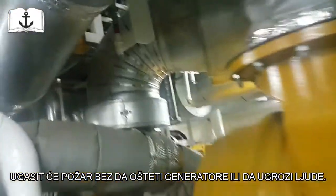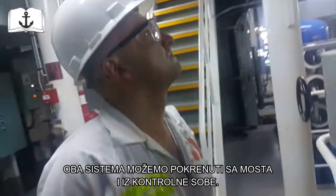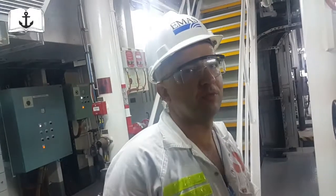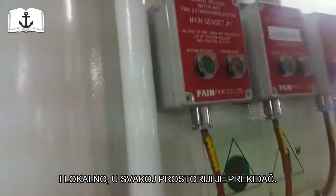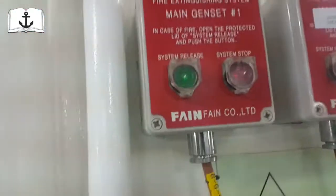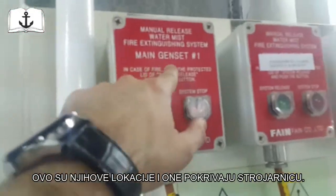Yeah, there's one more there. CO2 system. So, this one and this one, you can start from where? I can start it from the control room and locally. In every room there is a manual release. Main genset 1, fire extinguishing system, fuel oil purifier. So these are the locations where they are.